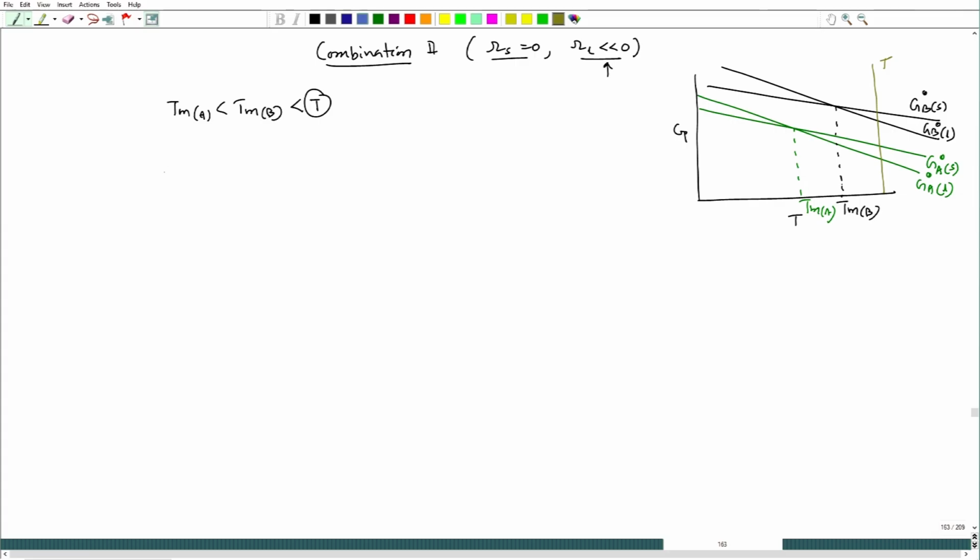Now, at that temperature, what will be the relative positions of delta G mix as well as free energy of liquid. We will be doing it on the same plot, and only after that will we do it at different temperatures. So, these are 0 points, x b equal to 1, x a equal to 1, and x b is varying this way, and we are doing it at temperature T. Now, at temperature T this would be G b naught liquid, this should be G A naught liquid, because that can be considered as 0.